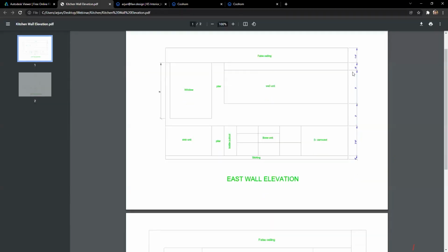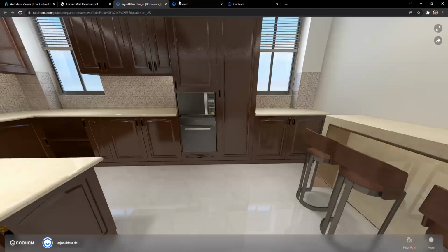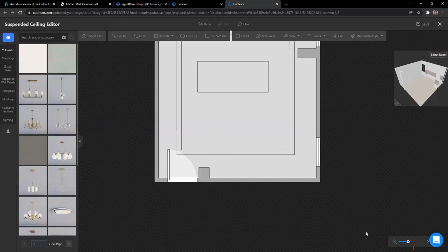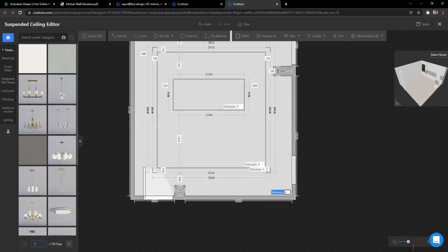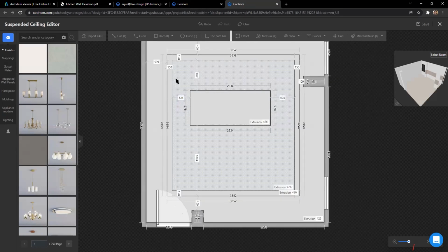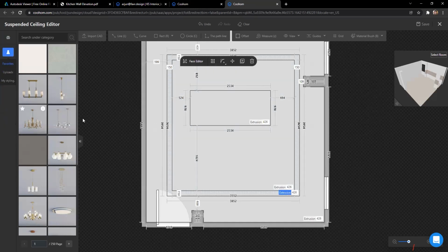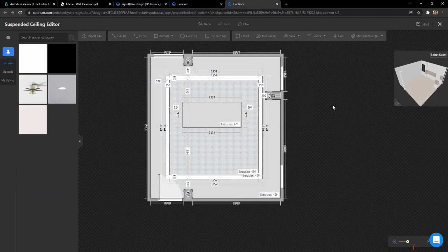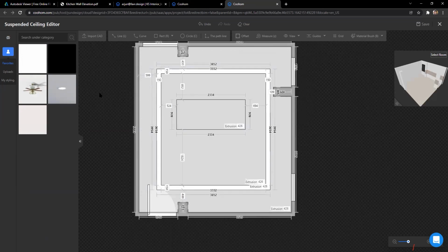In the elevation here, the whole ceiling comes under 1 feet 4 inch. So I'll have to extrude the whole ceiling to 1 feet 4 inch, which will be 426 mm. Here I'm going to apply a luminous object here so that this portion will glow when you render.